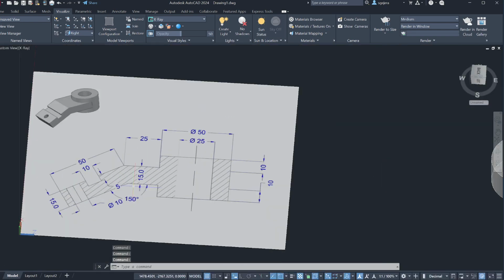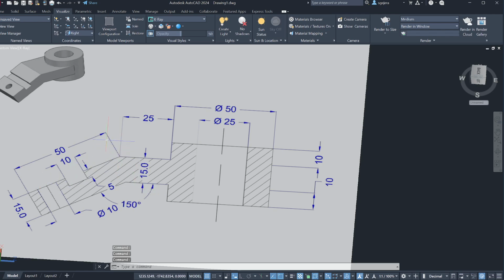Next, we want to create this one. And thankfully, the dimensions here are already aligned. So this is a full 50. We can do the base first, and then carve out the necessary features. We'll carve this out, and we'll also carve out that circle. Okay? So it's 50. We can just draw a line, 50 going there, then 15 going here. Then we can extend this line and, where it hits here, trim out the excess.